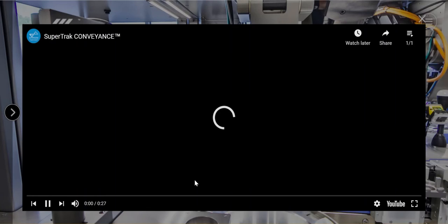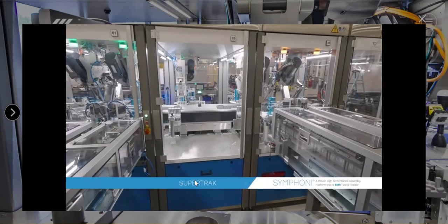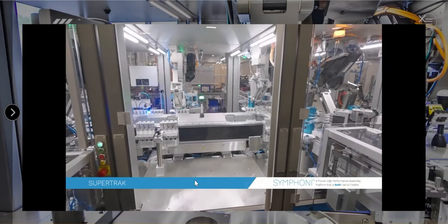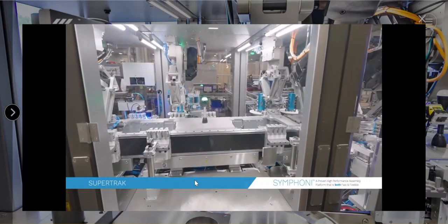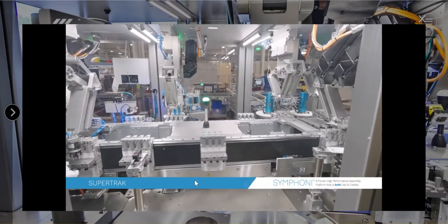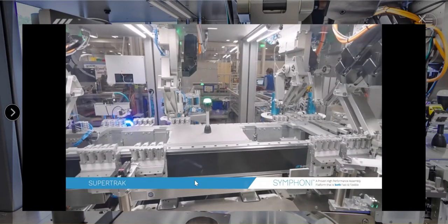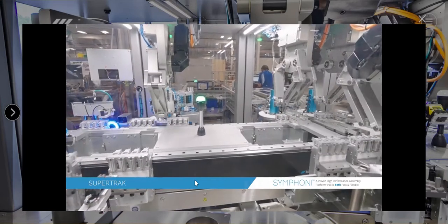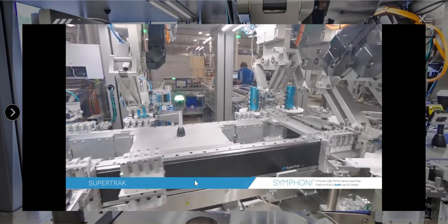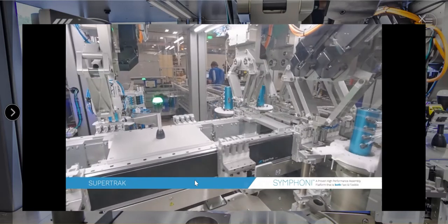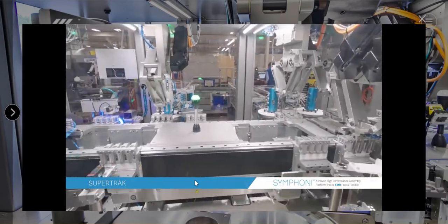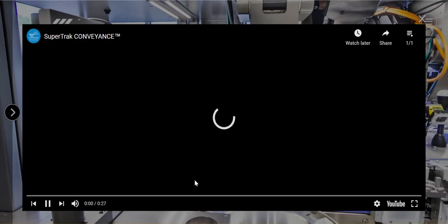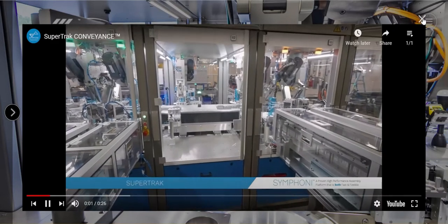And you see, we'll let that run one more time. You see again the pallets themselves moving through the system by electromagnetic force. You'll see them positioning, stopping at various positions depending on the operations that are required. You see quick accelerations and decelerations and presentation at individual stations, which is perfectly timed to coincide with that station's required operation.